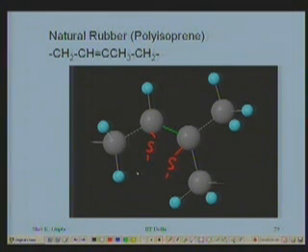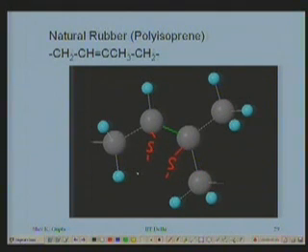Now it becomes a solid mass which can be used as an elastomer. It is going to be a soft rubber if I do the cross linking 0.5%. It will be a hard rubber if I do a cross linking of 5%, 10%. It will be still harder if I do it 20%. But if I do 100% cross linking, every double bond is broken to form a single bond. This will become a network, because this is connected to something else, that in turn will be connected to something else. Like that, the whole thing will become a network. So the two rubbers are very different.